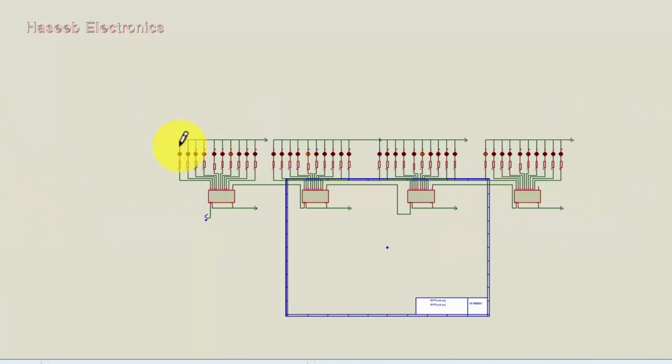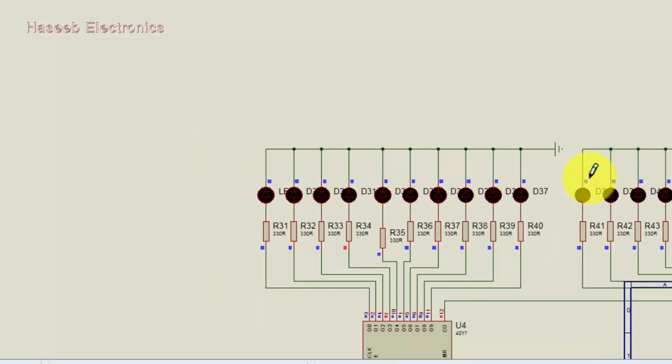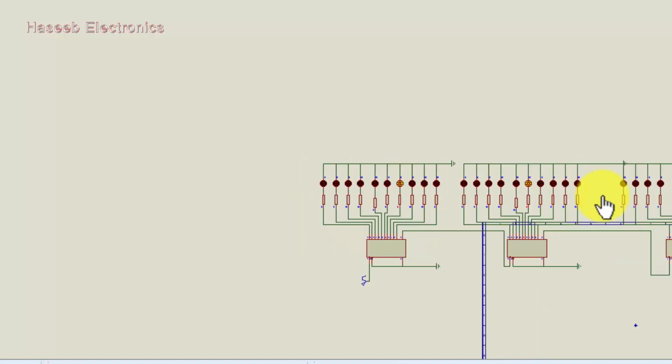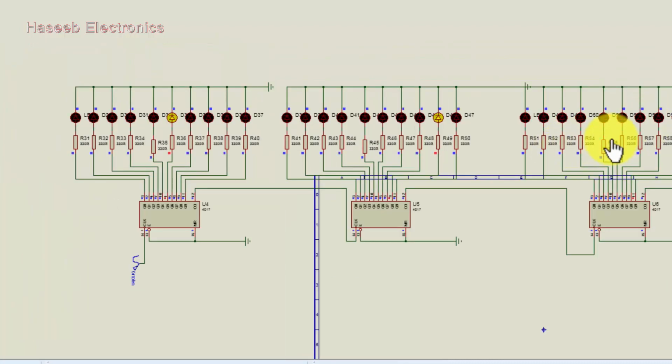The first stage is very fast because it is driven at 50 Hertz. The second stage is slow. It will divide by 10, it will receive a 5 Hertz clock cycle, and then it will receive a 0.5 Hertz cycle. Every cycle will divide by 10.